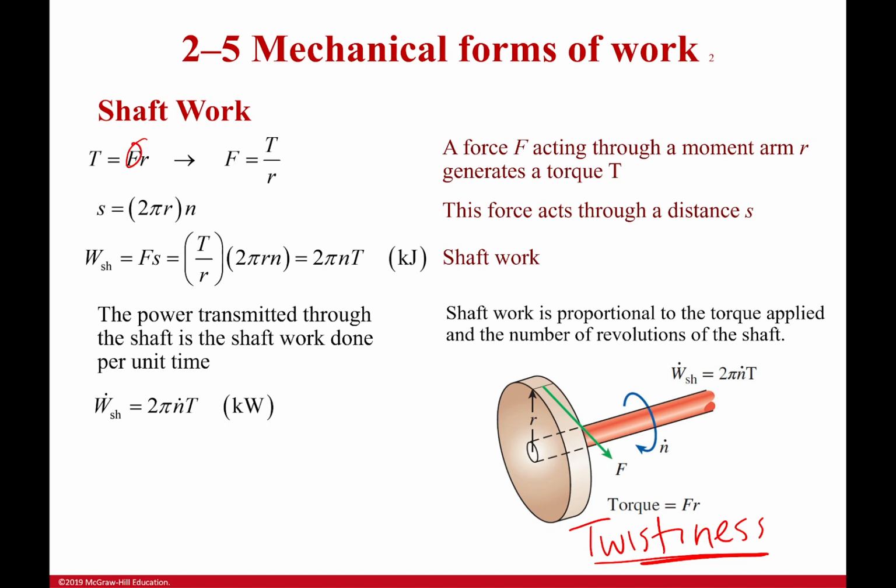It's simply a force times a distance from the center of your shaft. So you can see that distance right here. Another thing it doesn't show right here in the picture is that those two have to be perpendicular to each other. If the force isn't, then only the perpendicular component matters. So if I had a situation like this, here's my distance, here is my force going off at an angle, I would only care about this component right here, the perpendicular component, not this component right here. That one wouldn't do anything.